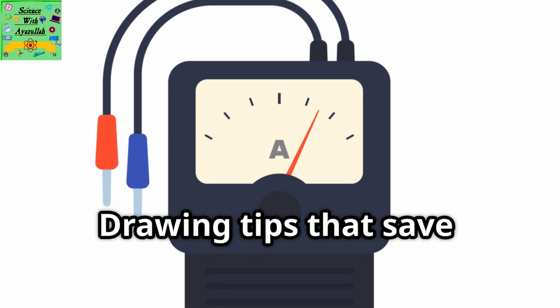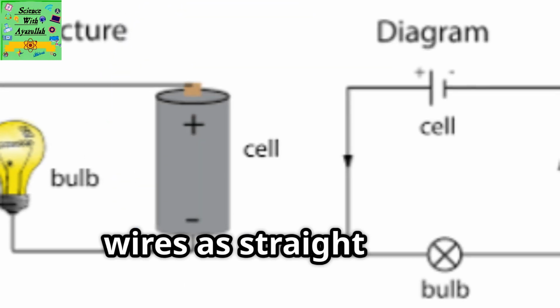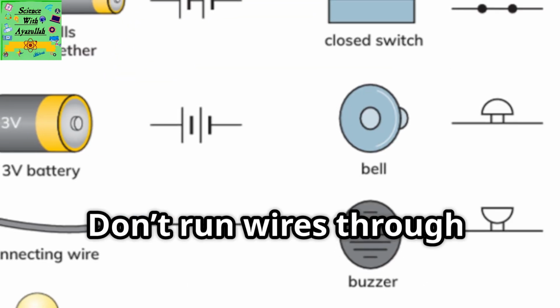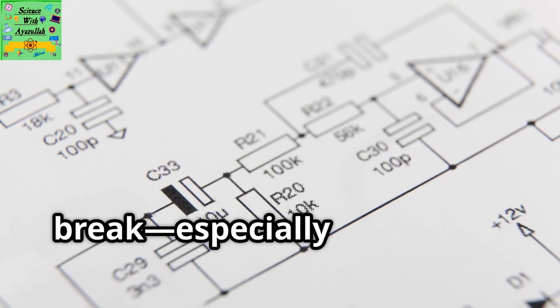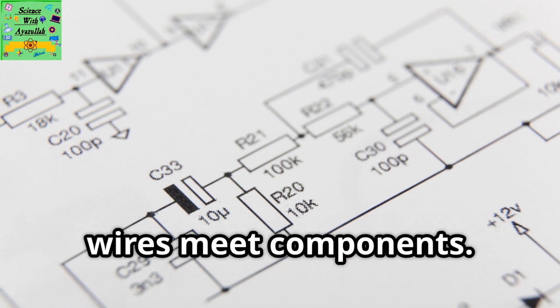Drawing tips that save headaches. Keep wires as straight lines. Don't run wires through symbols. Go around. No tiny gaps unless you mean a break, especially at corners and where wires meet components.